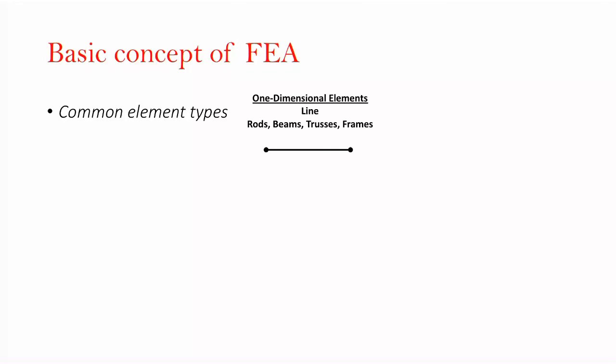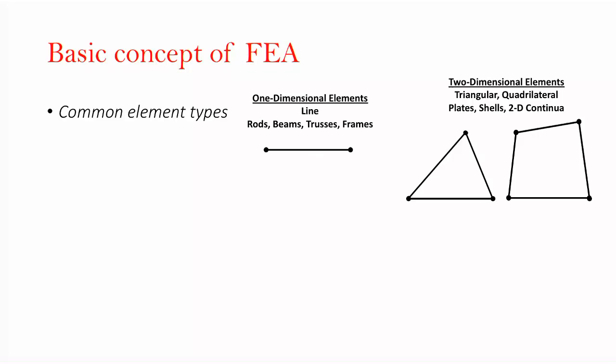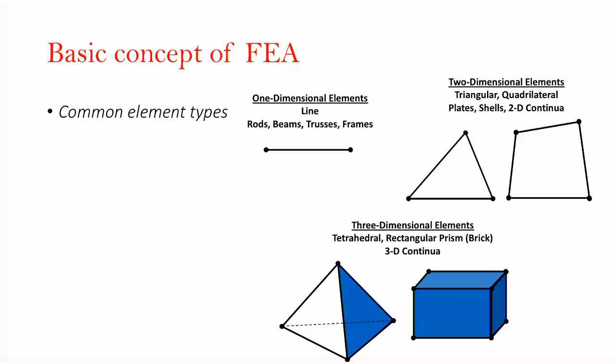We have 1D elements, like the temperature distribution that we used. Probably you heard about these elements: trusses, beams. Or it could be 2D, a two-dimensional element. Based on the shape, it could be a 4-node, like a rectangle, or a 3-node, like a triangle. And the most complex element is the 3-dimensional one, which could be like a cube, or a brick, or a tetrahedral element.